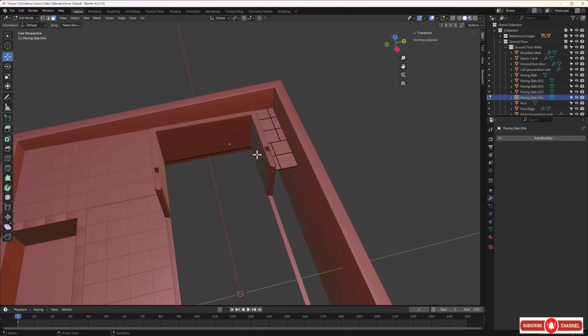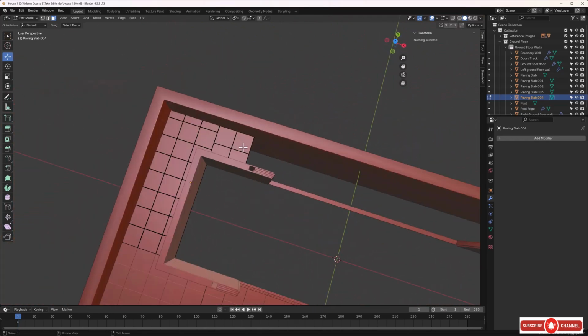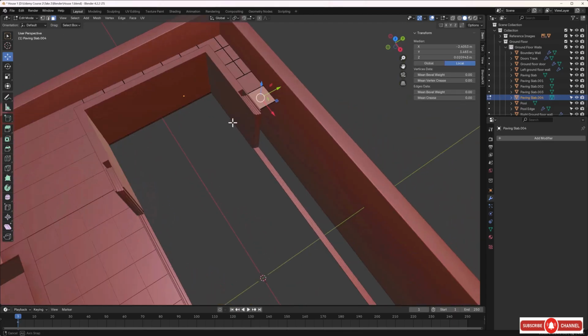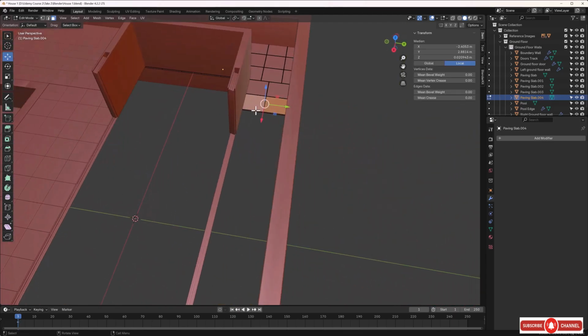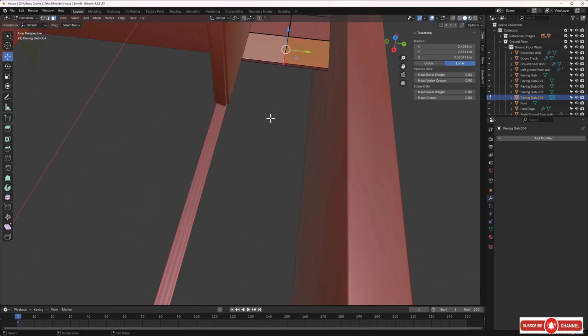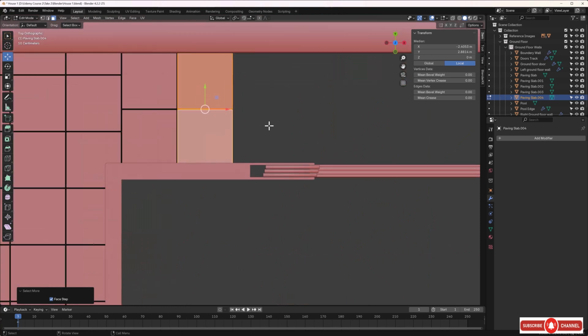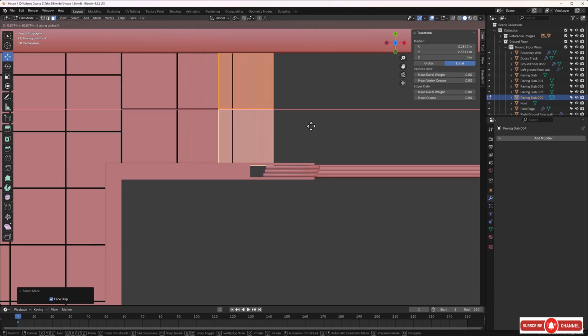So the next thing I need to do is actually to make a duplicate of these two here. So I'll do that. I'll select this face and this face. And let's hit Control plus to select all those faces. I'll press 7 again to get us the orthographic view. And I'll press Shift D and X and bring us a copy out like this.